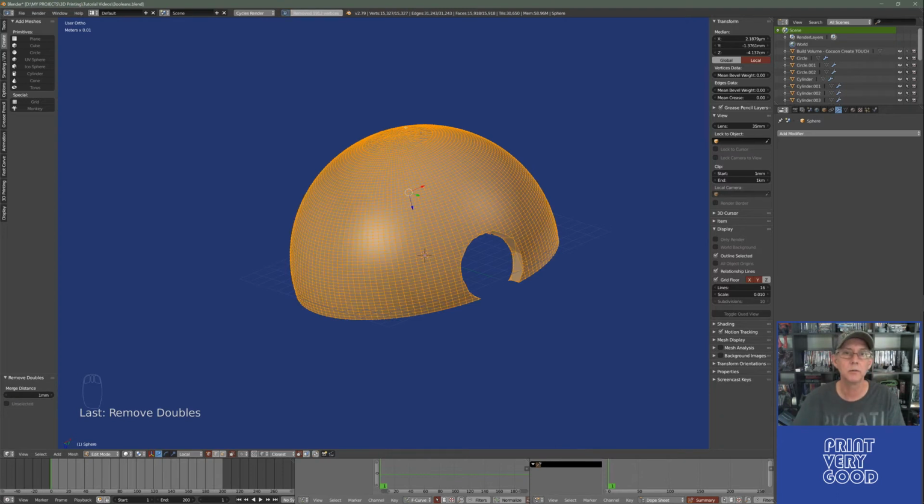And you can see at the top of the mesh there, it's starting to remove the vertices that are close together. And I'll just slide all the way to the left, and it's removed one vertex. So there was one vertex in there that was doubled up. What that basically means is, after the Boolean operation, there were two vertices sitting on top of each other, or one piece of mesh was touching the other piece of mesh, but they weren't joined.